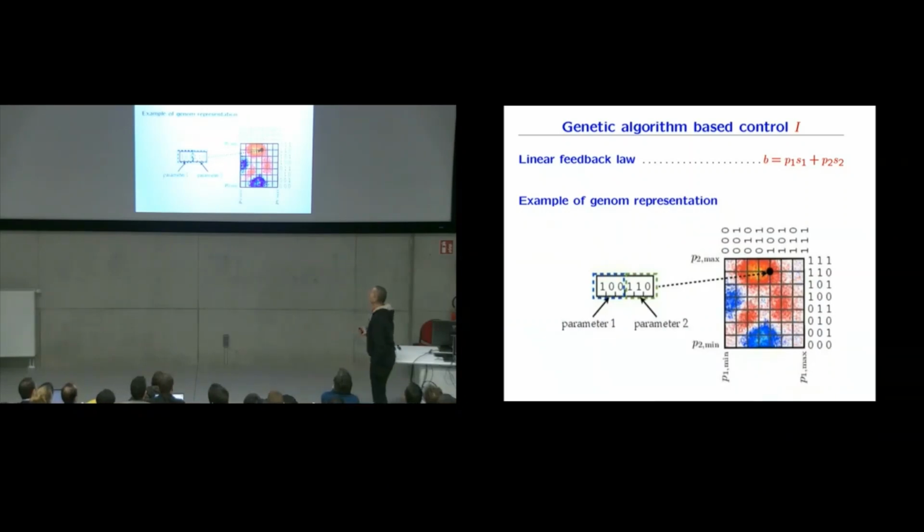No. So what you are doing here, now you discretize your parameter in a kind of funny way. You say, I discretize my parameter in terms of 3 bits. There's a value here corresponding to the bits 0 0 0, 0 0 1, and so on, and 1 1 1. So you discretize your parameter in 3 bits, and the other one also in 3 bits, so that if you put these together in a 6-bit string, this characterizes your controller.